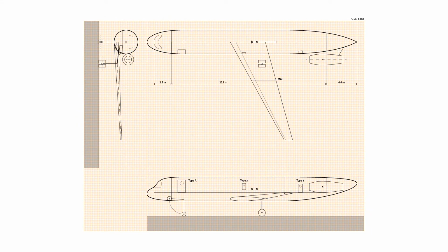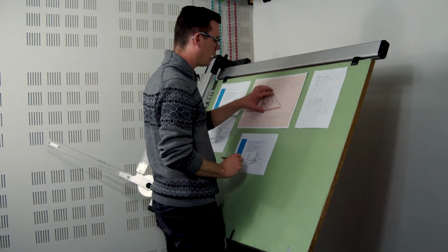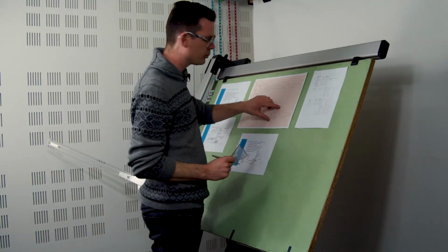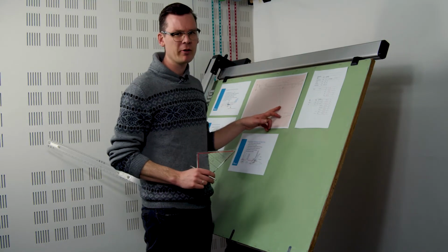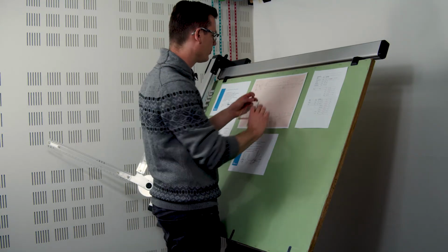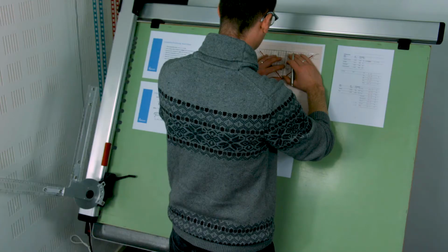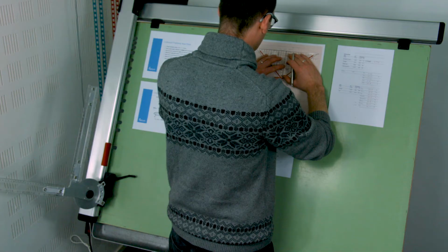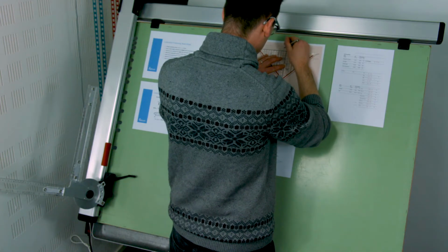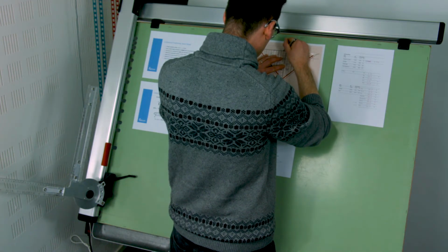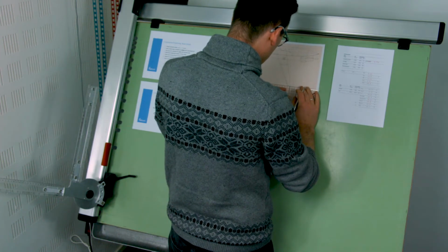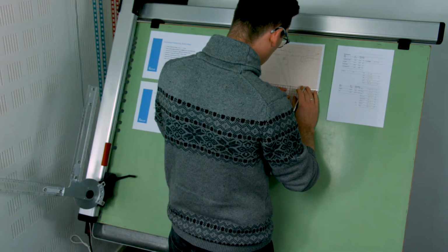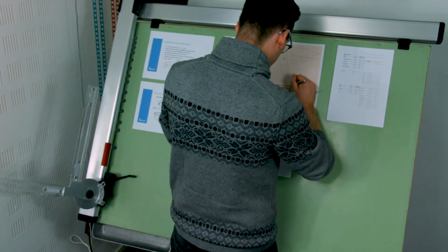So my spar is going to be located over here, and my aft spar, my rear spar I should say, I want to leave at least 25% chord open. So on my root chord, that is 1 meter 25, coinciding with the aft CG, and on the tip it's 25%, it's 40 centimeters.